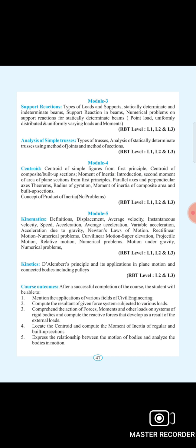If you want to do anything, you need the properties of a cross section, which has the centroid and the moment of inertia. That will be calculated here with two theorems, the parallel axis theorem and the radius of gyration. That will help you resolve the geometrical cross section to find the centroid, as well as, in terms of the x-axis or the y-axis, the moment of inertia.